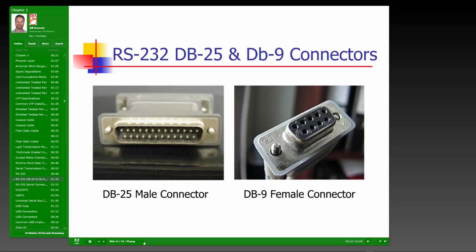But again, we're talking about the RS-232 standard, which is used for communicating information between two devices. Believe it or not, even though we have all these pins in these connectors, it is still serial communications. In other words, we don't have different streams of data being carried over each of these pins.